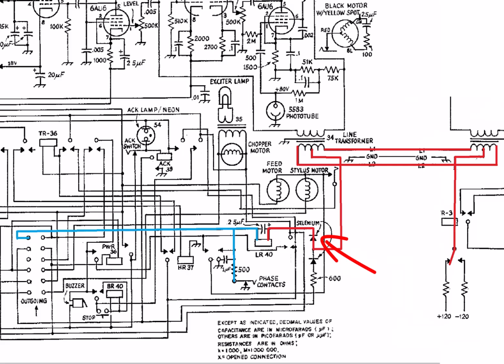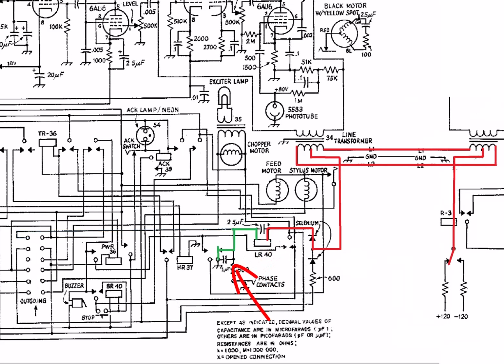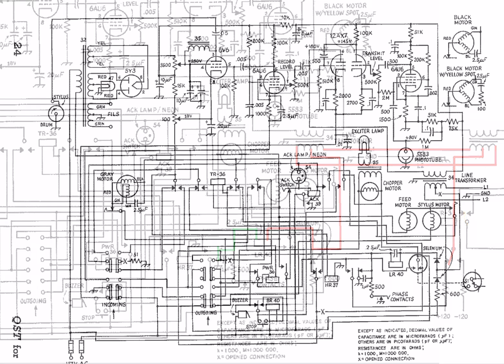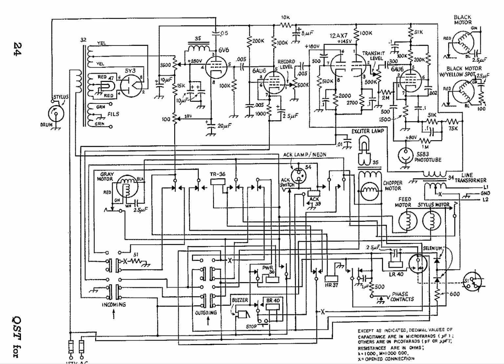And then when the central office applies a positive voltage to the line, then this upper selenium rectifier is forward biased and the central office voltage is applied to this line relay. If the DeskFax leaves the other terminal of that relay open circuit, then no current flows through that line. But if it takes that terminal to ground, then current flows through from the central office, through this relay and into ground, and then this relay is energized and closes. Of course, at the same time, because current is flowing, the status relay at the central office will also close.